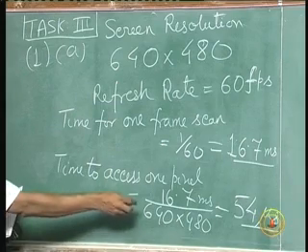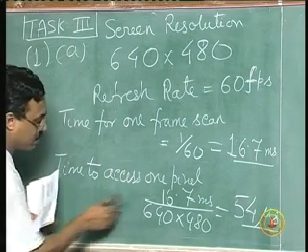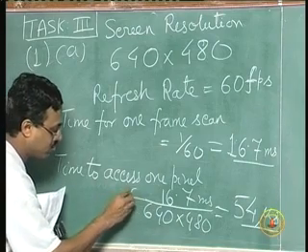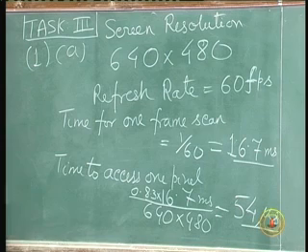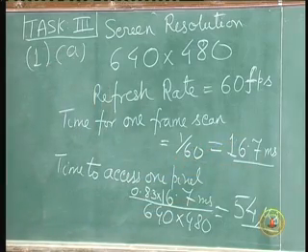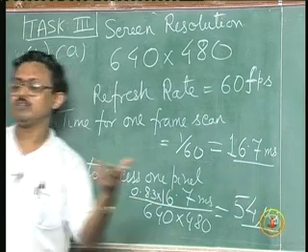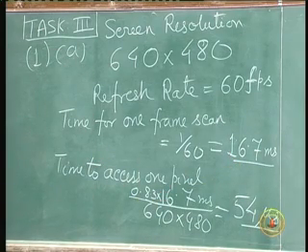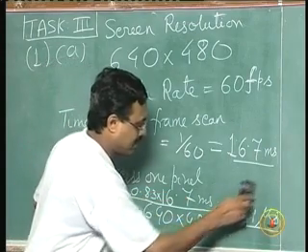So, for this value of 54 microseconds you need to put a multiplying factor of about 0.83, assuming 17% of the time is gone for retrace per frame out of the 16.7 milliseconds. If it is 15% for retrace, then you will have 0.85. So, that value goes down by some amount.